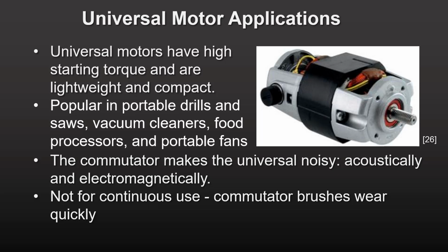The commutator makes the universal motor noisy. One reason why the previously mentioned products make a lot of noise. They also emit a lot of EMI noise, and they can throw off the performance of any nearby electronics design. Some companies use power drills as a quick and dirty way to test the EMI susceptibility of their prototype electronic